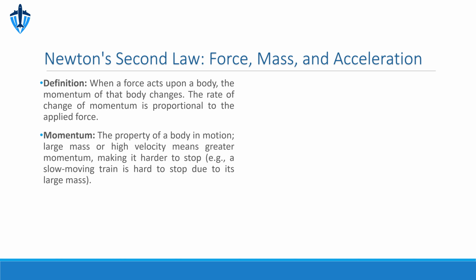Let's put the formula into practice with an example. Imagine a 10-pound weight moving in a circular path with a radius of 3 feet at a velocity of 500 feet per second. What would the centripetal force be? First, we need to convert the weight to mass by dividing 10 pounds by 32.2 feet per second squared. Then, we plug these values into our formula. Force equals mass times velocity squared divided by radius. So, it's 10 divided by 32.2 multiplied by 500 squared, all divided by 3. Performing this calculation gives us an approximate centripetal force of 25,880 pounds.